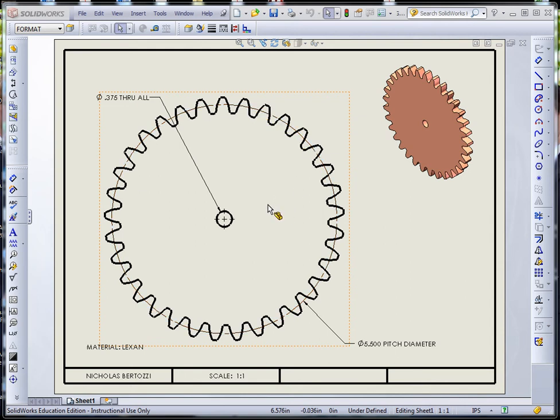So if you had a pitch diameter of one gear with 3 inches and the other gear had a pitch diameter of 1 inch, then the ratio between the axles rotation would be 3:1. So anyways, this will be what we'll end up with at the end.